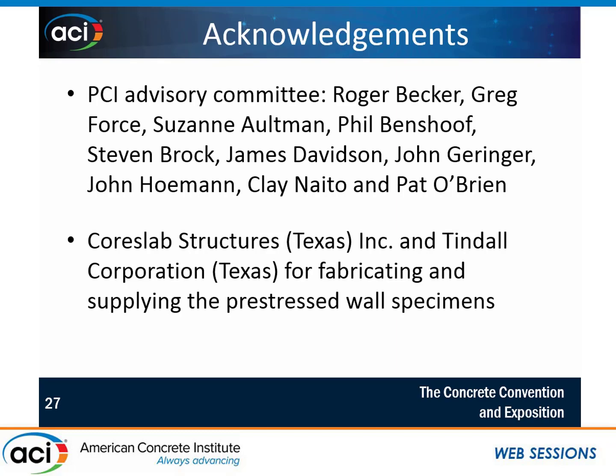Yep. So damping we neglected. The inertial term, we actually did something similar to what Matt had with KLM factors. We determined what those KLM factors were as well, based on the actual displaced shape. So we weren't only changing the resistance, that's really what I showed here, but we were also changing KLM.